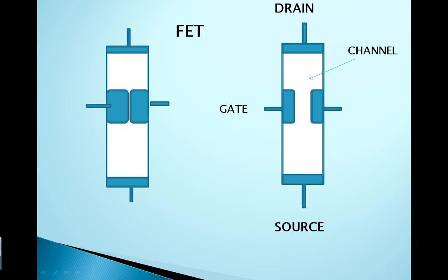The effect of this gate voltage can best be seen here, where you can see on the left hand side a big negative potential which has closed up the channel, and on the right hand side the channel being open to allow a lot of current to flow through.